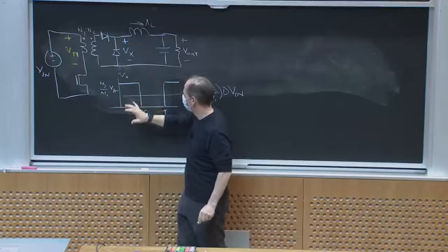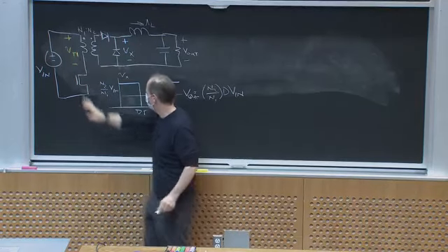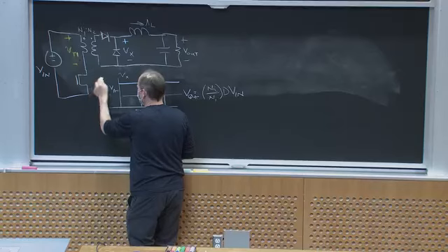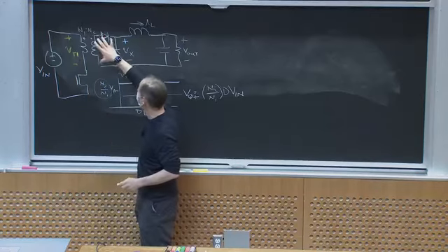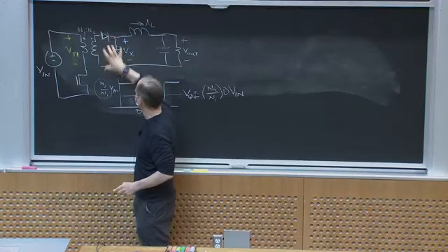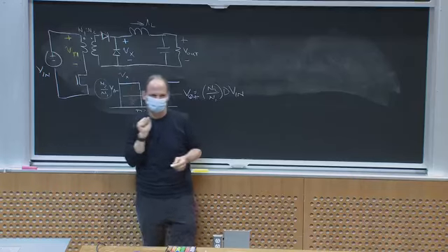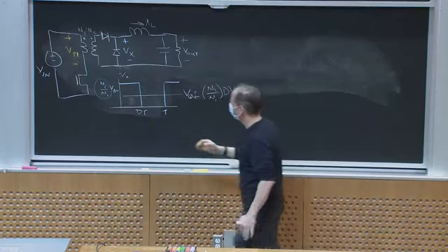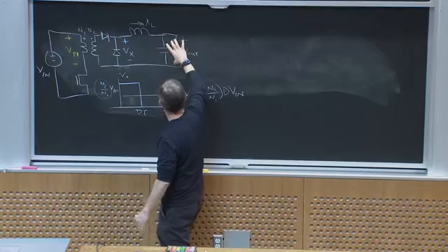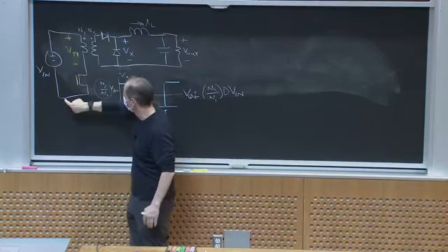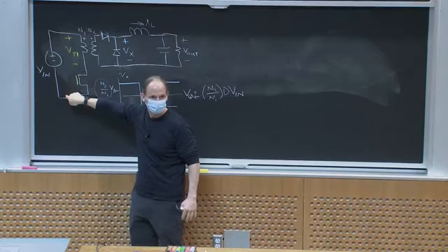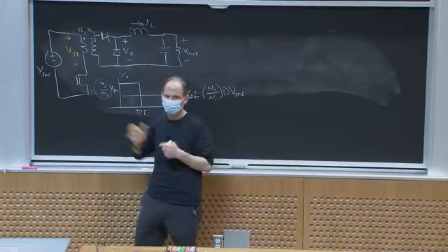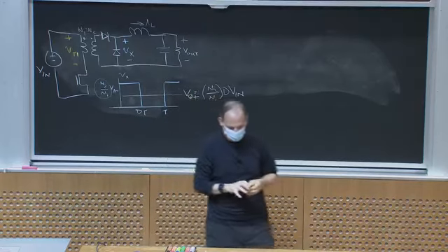And what I've gotten out of putting this transformer in here is this scaling. Instead of applying the input voltage directly here through a switch, I'm applying a scaled version of the input voltage, and I get this nice rescaling. And I also get the electrical isolation. This port is no longer referenced to this node. Okay, so it's some of the same advantages. All right.